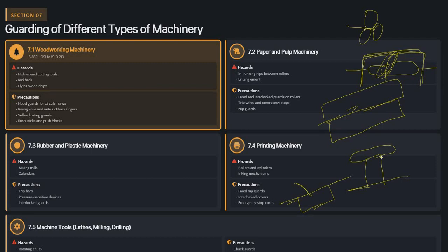Then this emergency button, what happens? Can I stop the emergency by pressing with my head, with my shoulder, with my body? I can stop this. Is it right or wrong? Understood or not? In a push button, we can do it only with fingers. But emergency stop is different. If fingers got caught, then we need to stop it by our body, by our shoulder, by our head, by our leg, whatever is there. But push button is different.